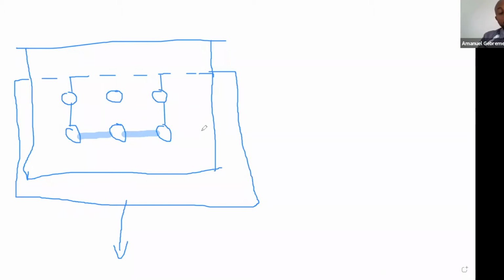That's the model that we use. These failure limit states are actually much more complicated when you test them in a lab, but this is the model that we use. And we say, all right, this is failing in tension, this is failing in shear, and the combined failure is called shear block failure. This is a real failure limit state. It's been exhibited in real structural failures, as well as in a lot of tests.